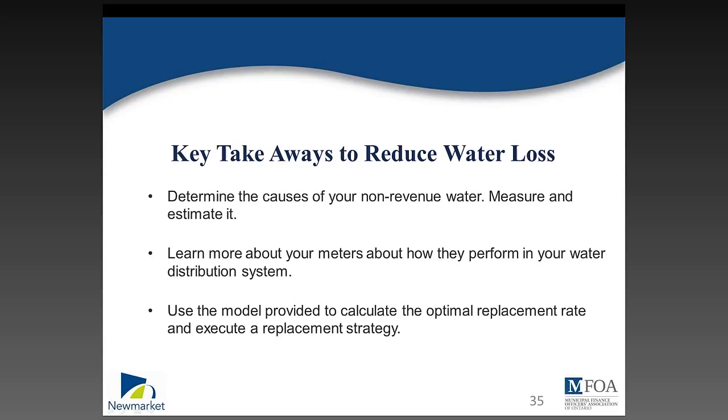Key takeaways to reduce water loss. Determine the cause of your non-revenue water and measure and estimate it. Learn more about your meters and about how they perform in your water distribution system, and use the model provided to calculate the optimal replacement rate and execute a replacement strategy.